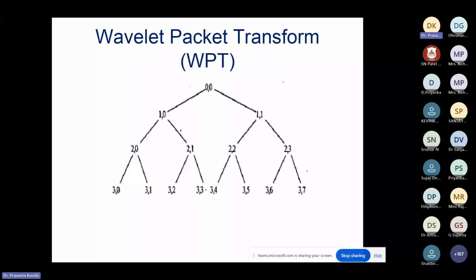If one is giving 90%, still 10% is left; another will give another 90%, and the combination of both will give fewer chances of error. That's why wavelet packet is also used, with similar decomposition levels. Another addition here is that the approximation is also decomposed into two different levels. Previously, only the details were decomposed; in wavelet packet, both are. So you'll have many signals and different cases we can identify. It is also time frequency analysis.